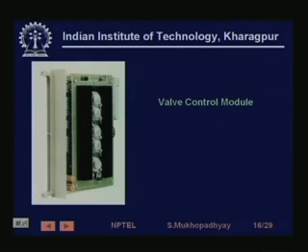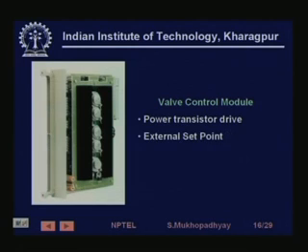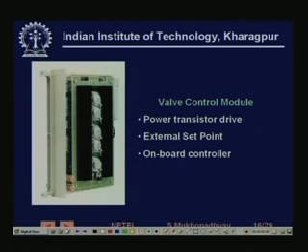This is another controller, which is a valve control module. I chose this because I wanted to show the power transistors on it. You can see the power transistors. Valve means it's probably a hydraulic servo valve or something, so it has to pull a solenoid, create some force so that the piston moves.